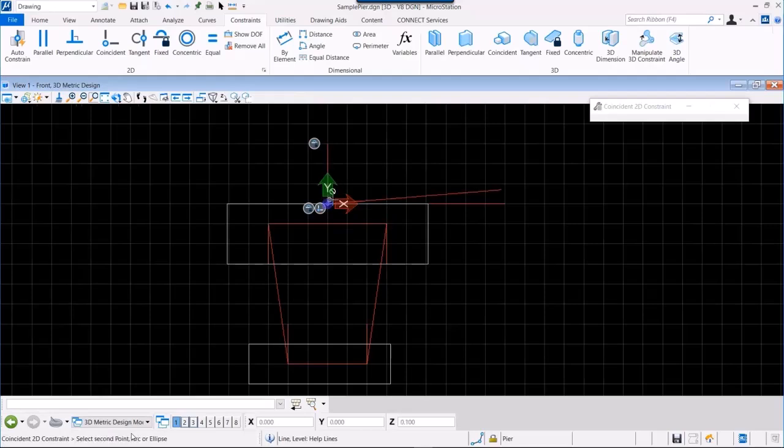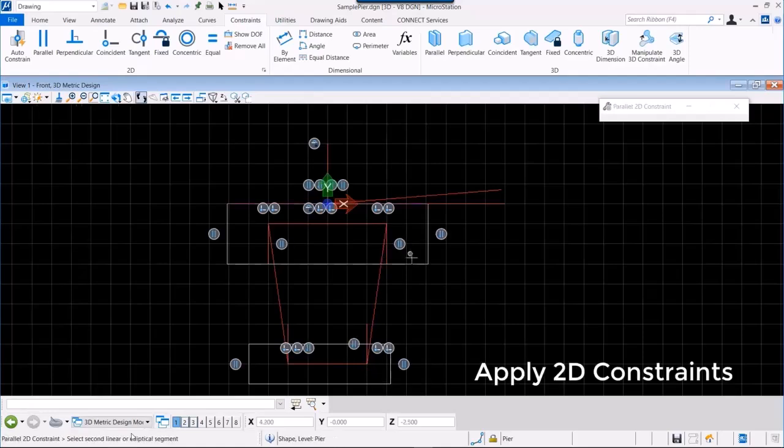And these two lines will remain perpendicular no matter what, right? So it's just, again, defining kind of a coordinate system. Done. And the same with my help lines, they will remain connected and perpendicular here. And then this point also will be fixed. And then the perpendicularity on that. So I just defined it.